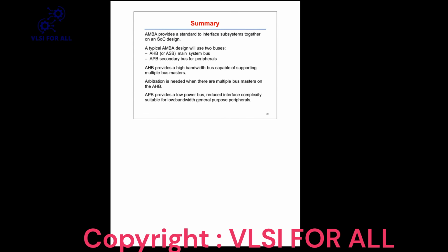Like the FIFO concept, we know the FIFO or buffer concept. What it does is it stores the data temporarily, and whenever the slave or receiver is ready, it gives that data, but with a certain delay. That delay is provided through the bridge. That is where we require the AHB to APB bridge basically.